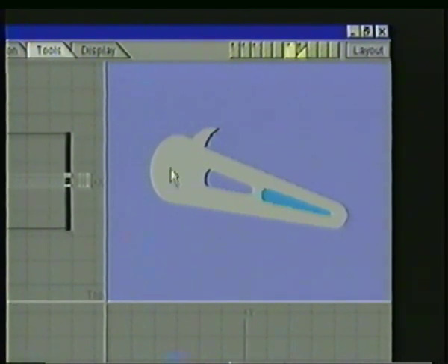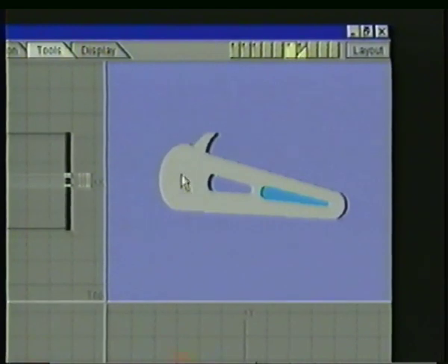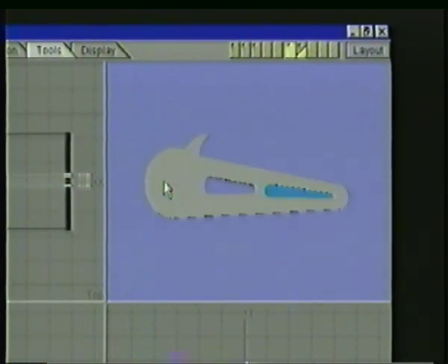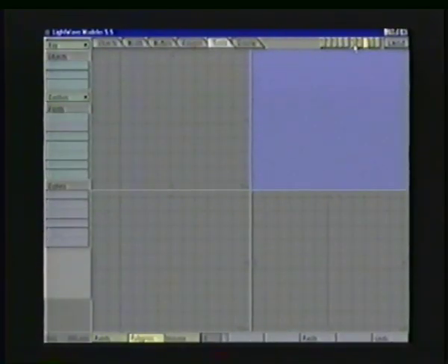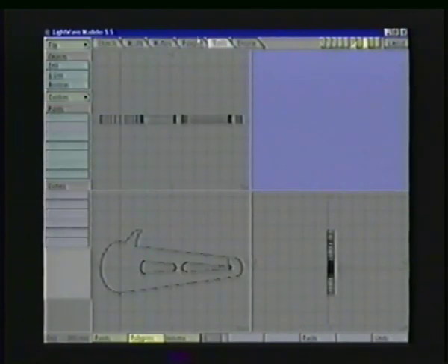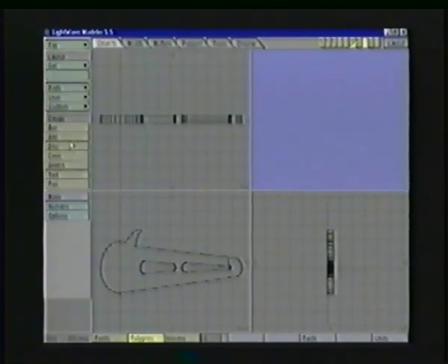What we're missing here is the detail at the pivot point of the leg, or the joint of the leg. Instead of having to make a cutting tool first and then Boolean subtracting like we did just now, there's a much more simpler method. And once again, I'm going to go to a new layer and put the leg in the background. We're going to use the Disk tool.